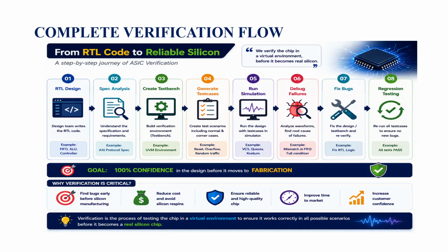If there are no errors in the testbench, we go to the RTL engineers and say, this feature I am verifying is mentioned in the specification, but when I give this input, it is not supported. It is a very simple way of approaching an RTL engineer if we find any RTL bugs. After we debug the failures and fix the bugs, we have to run the test case again.